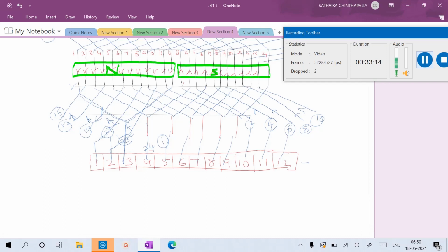Now, based on the current direction, second step: under the north pole we assume the current direction in the conductor is downward, and in the south pole the current direction is the opposite, upward. Here we are going to get two conductors in the same direction. If you observe here, the first conductor's current direction is downward, and at the same time the 12th conductor is also downward. That means both conductors' currents are downward, connected to the number 3 slot. Now the current is collecting here.